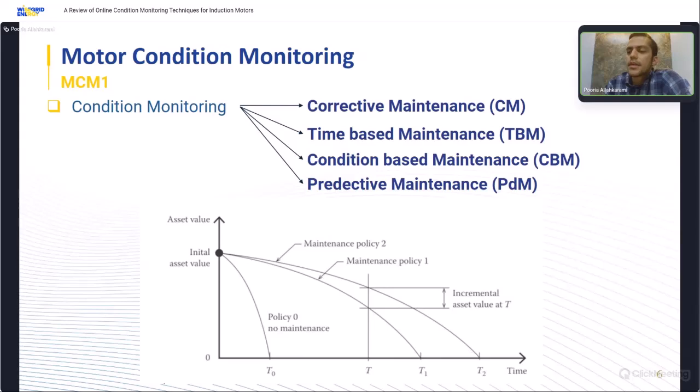But the main drawback of this method is its accuracy. TBM is based on average data, the average lifetime of the asset, for example, the manufacturer's mean time before failure, rather than the actual condition of the asset. For example, consider a part that is working but is replaced too early, even when it has suitable lifetime remaining. This leads to over-maintenance and wastes time, labor and materials.